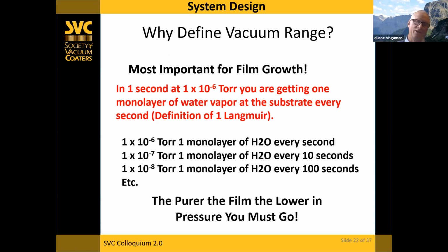Why do you need 10 to the minus 10? And I think you hit on it on this next slide as well. Sure. So again, my area of interest is in thin film growth. And I know this: the lower I go in vacuum, the less I expose my substrate and my film to water vapor contamination.